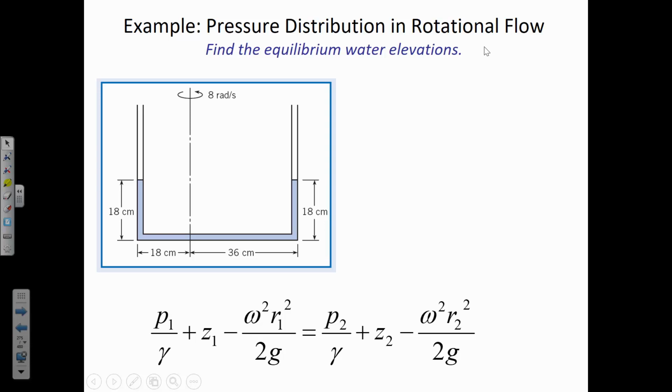But basically what this means is, another way of putting it is, if the water goes down 1 centimeter on the left, that water has to go up 1 centimeter on the right, as long as the diameter of this tube is the same. It would be altogether different if the left leg was a smaller diameter tube than the other one. Then we'd have to look at the ratio of the areas to know how the Z's were related. But does everyone get that idea that if we're spinning it around such that it went down a little bit on one side, it's going to have to go up the same amount on the right? There's conservation of volume of water. It's just its location changed.